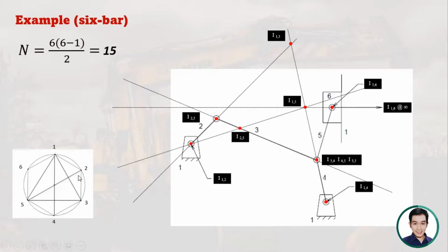And then another triangle that we can locate in the IC circle is 3,6. So if you connect 3,6, you can get the sides 1,6,3 and 3,5,6. So we have 1,6,3: 1,6 and 1,3. So our 1,3 is located here. So this is the 1,3. And then the 1,6 is infinity, so therefore it should be parallel to this infinite 1,6.